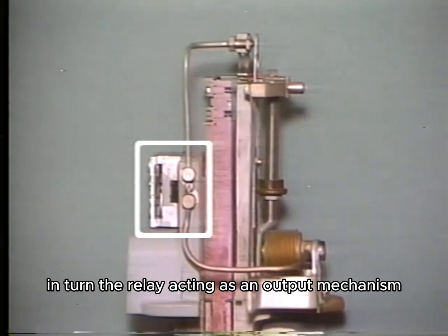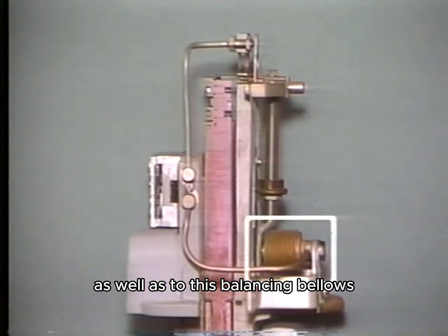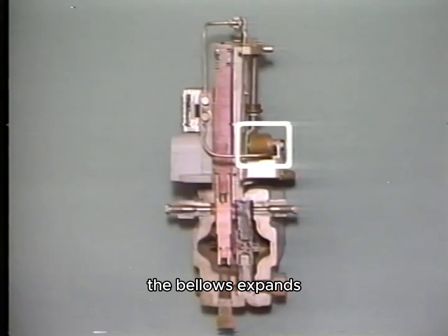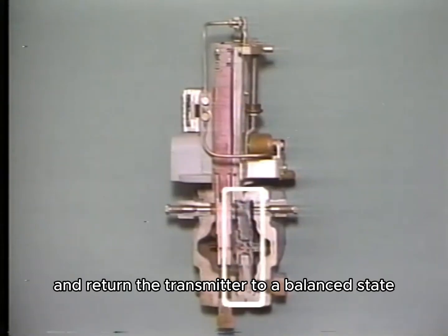In turn, the relay, acting as an output mechanism, creates an output pressure. This pressure is sent to another instrument as well as to this balancing bellows, which is the balancing mechanism for this transmitter. The bellows expands or contracts to balance the differential pressure change to the diaphragm input mechanism and return the transmitter to a balanced state.